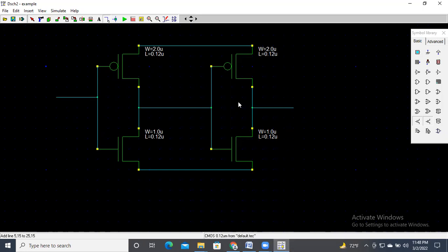What we are missing here are the inputs and outputs and the supply and the ground. So let us provide the input. Here we use a button as input. The button is here, and a lamp as output, to see the output. The lamp is here. Then we need to provide the ground. So this is ground, and also the supply. The supply is here, VDD supply.